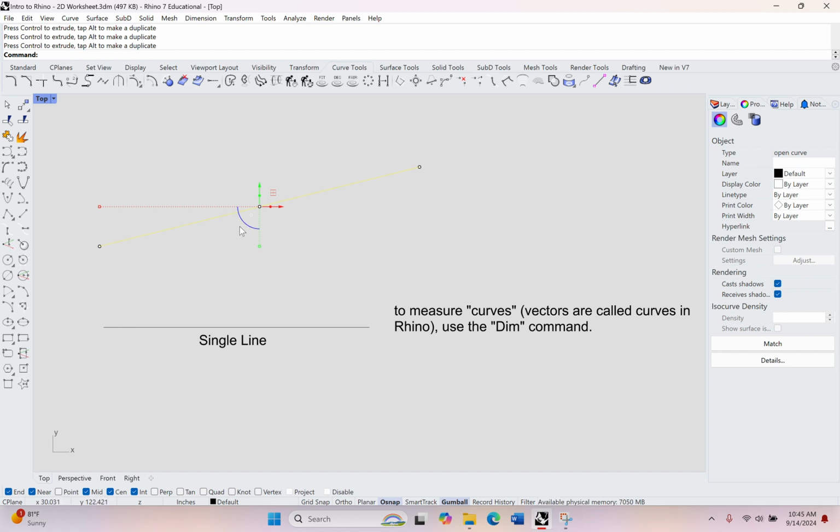And if I want to change the angle, I'll do the same thing with this little curved blue line here. If I want to adjust the angle in a very exacting way, I just click the blue line once, and then I can specify I want it to be 30 degrees, or if I want to turn it back the way it was, I'll click and I'll do minus 30 degrees.